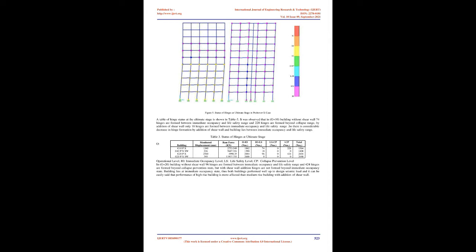As the building is symmetric, shear wall is provided in the central bay of the longer side of the building frame. M25 grade of concrete and Fe415 grade of steel are used in all members. Loads considered. The following loads are considered for analysis of all buildings. Live load, 3.5 kN/m2 on all floors, as per IS 875, Part 2. Dead load, 3 kN/m2 on all floors and 16.8 kN/m wall load on all beams.